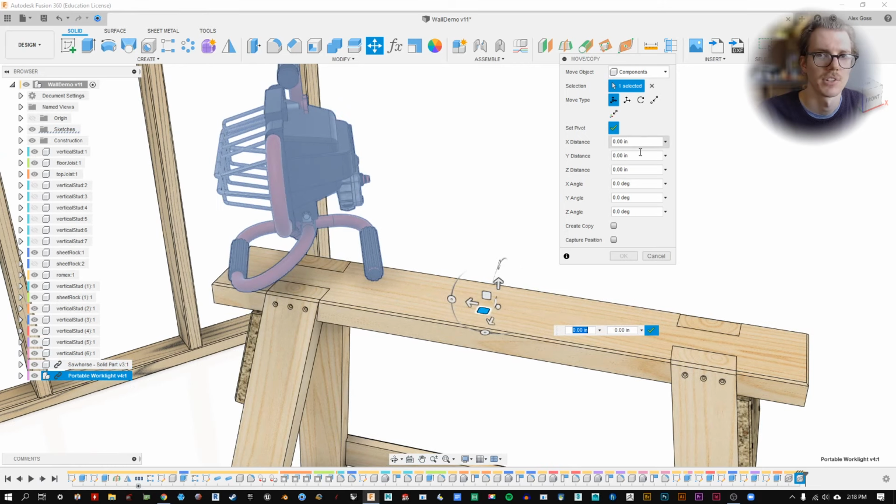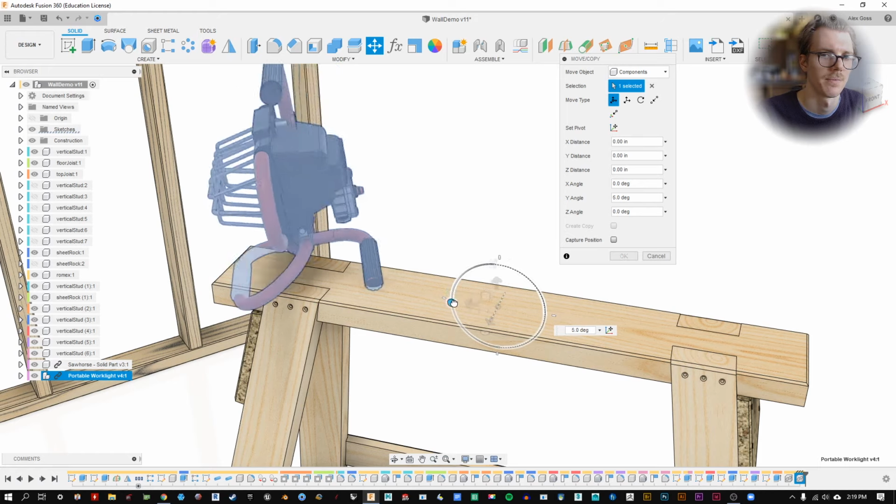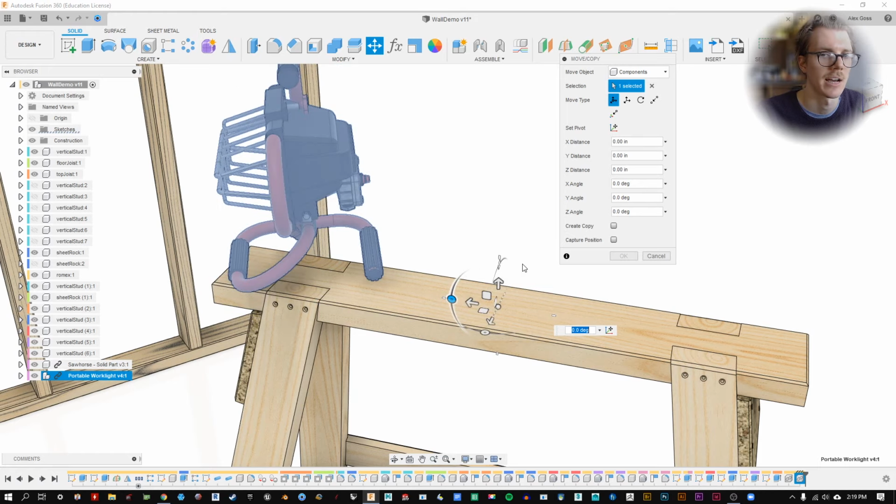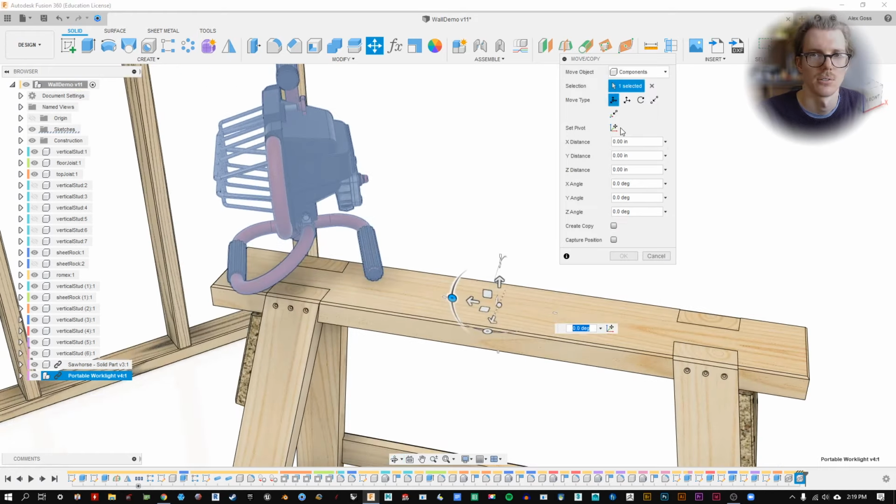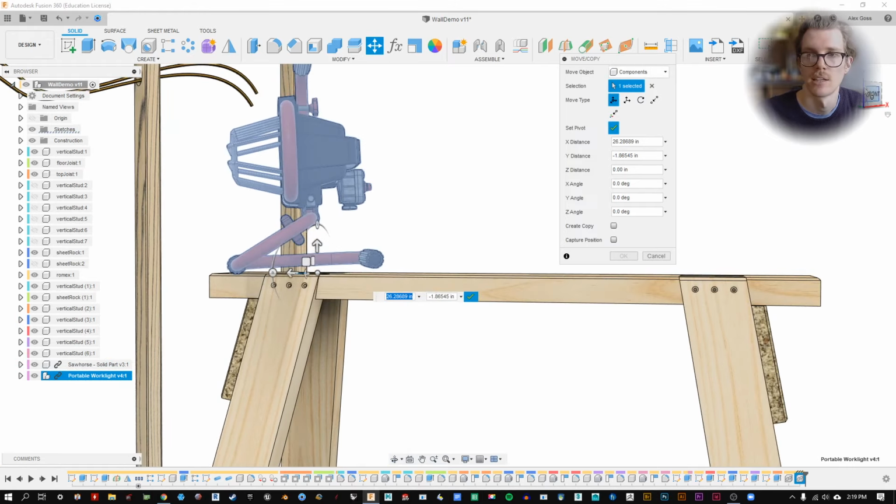I'm going to show us back here first. And then it's important we hit that checkbox before we try to move something, because we're just creating an additional offset now, which isn't what we were trying to do. So I'm going to hit check, and then notice I'm moving from back here. If that's counterintuitive, we can set that pivot somewhere really far away, and then we can move it close.